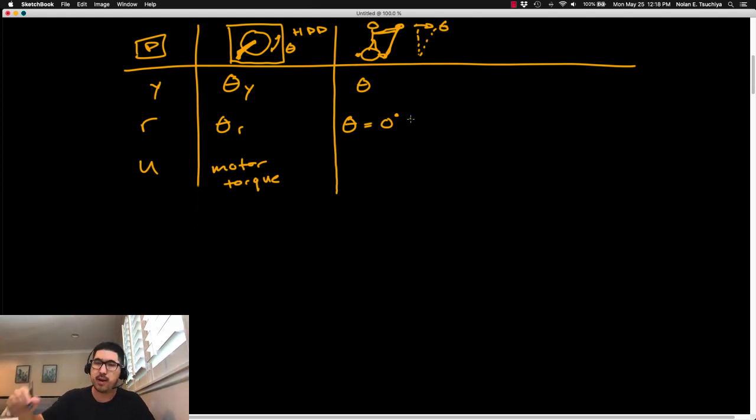Through the feedback loop, it's going to constantly monitor the current angle from the vertical and compare it to that reference. Based on whatever the error is, the controller block will send out a control command, which is again just going to be a motor torque to the wheels at the bottom. So if you start leaning forward, the control system is going to say, oh, we're leaning forward, you better drive those wheels forward to counterbalance that error signal. Try to bring that error back down to 0.